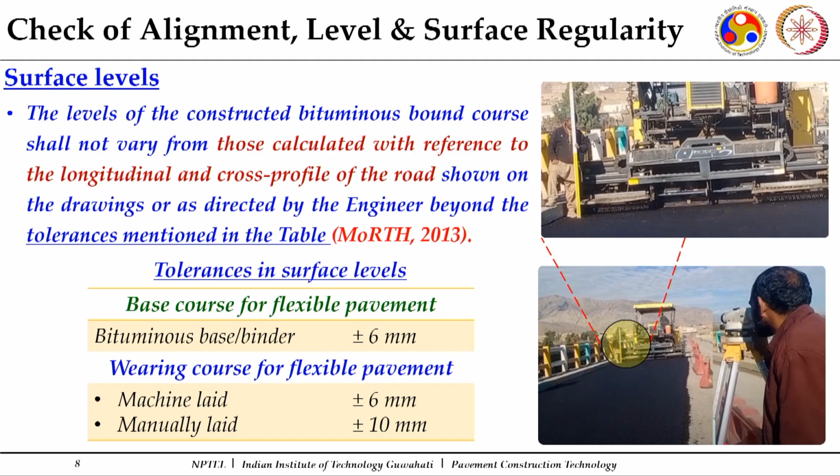Now, the surface levels, as I mentioned, should be ensured before the construction and during the course of construction. So this exercise goes simultaneously. You can see this is a surveyor, they are also engineers, so any one of us can ask them to install the staff and your total station, and you would prefer to have a continuous check over it. And as I mentioned in our previous lecture, for the compaction exercises, the laying exercises, and the number of passes, we need to have a trial stretch.